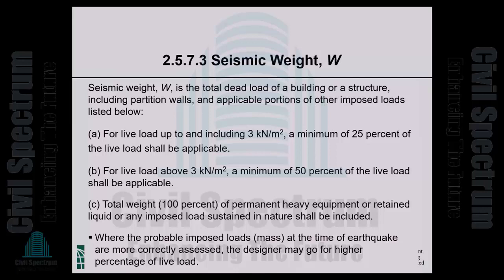It's extremely important that you understand the seismic weight is not the same as the weight of the structure. Seismic weight, in principle, is the weight that will be shaken by the design earthquake. So we typically include a part of the design live load in seismic weight, particularly for storage occupancies, because a warehouse is extremely unlikely to be totally empty when the design earthquake hits.